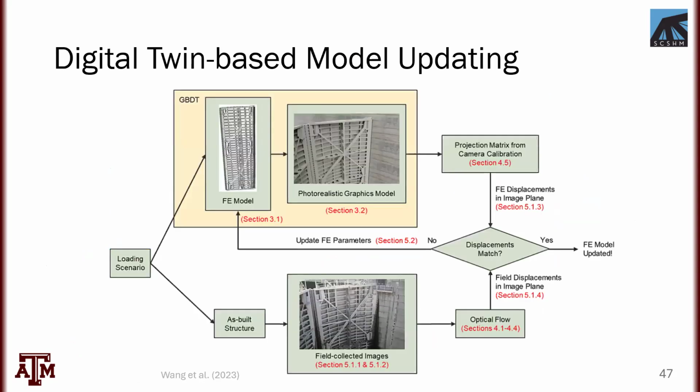So here's the digital twin-based model updating that they developed. It starts with this finite element model of these miter gates. There is a photorealistic graphics model that's also generated with all the textures, with all the colors, and pretty much all the realistic lighting conditions. Loading scenarios are applied. We kind of know what loading scenarios are because we can measure the water levels. And then optical flow is used on the field collected images and on the digital twin collected images.